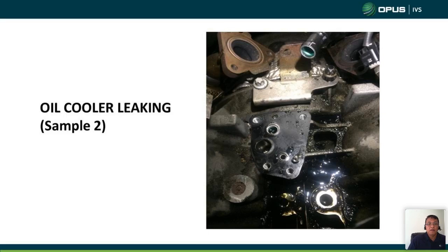So in this case, if you have an oil leak, or it's an inlet manifold motor issue, if you have an inlet port channel motor issue, I always recommend replacing this seal also for the oil cooler, because it will be only one job.